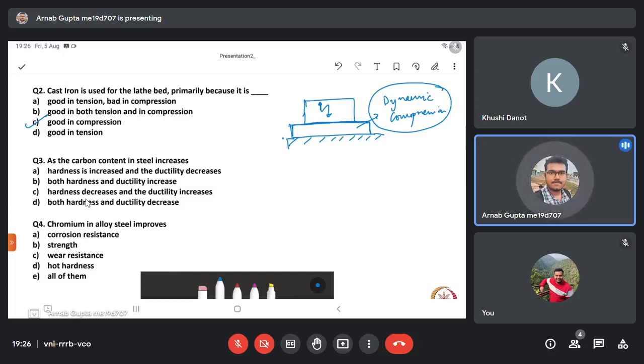As the carbon percent increases, the ductility would reduce, because carbon induces brittleness to the steel basically. But at the same time, it increases the strength of the material. Why does it increase the strength? Because it arrests the dislocation. As the dislocation is traveling through the material, so what is dislocation?